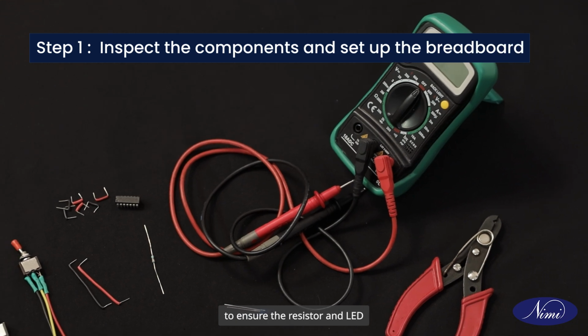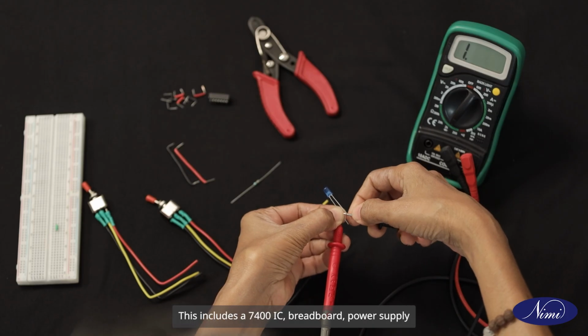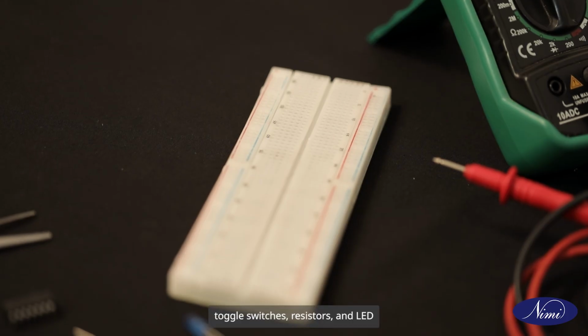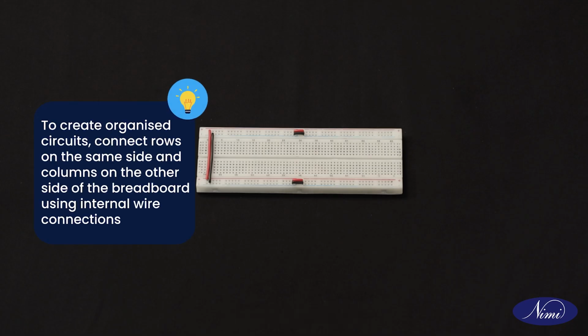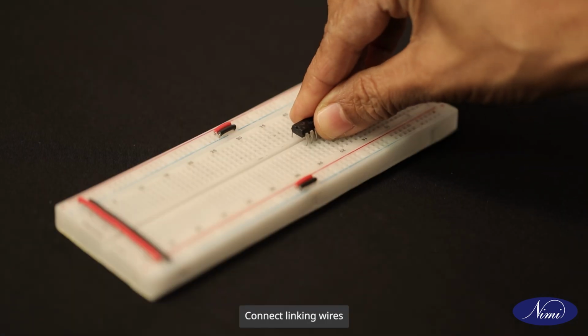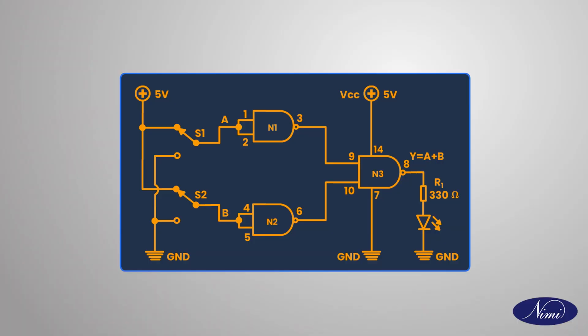Collect all the required components and check them to ensure the resistor and LED are in a working condition using a multimeter. This includes a 7400 IC, breadboard, power supply, toggle switches, resistors, and LED. Once you've got everything, mount the 14-pin IC firmly on the breadboard. Use the circuit diagram for reference.